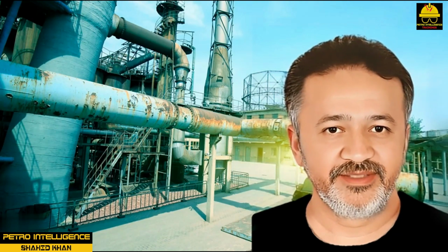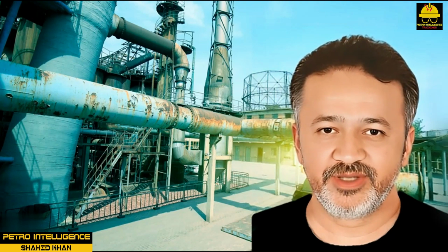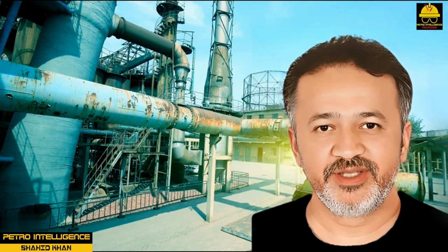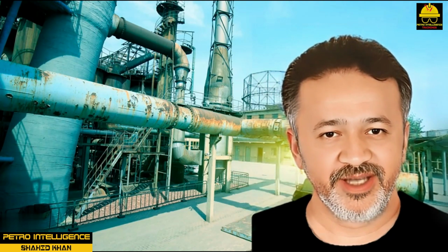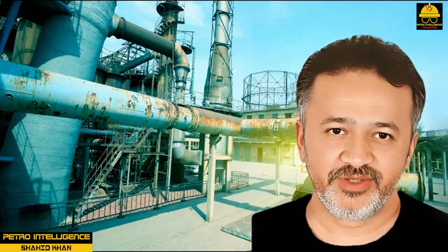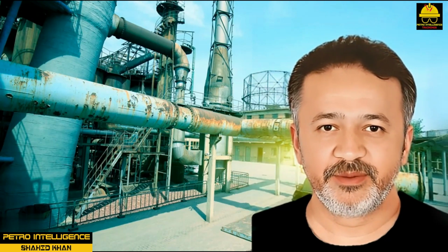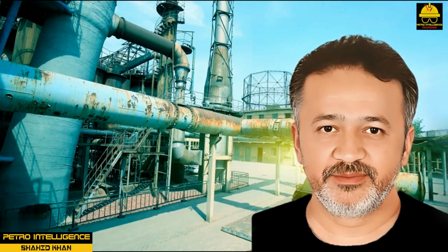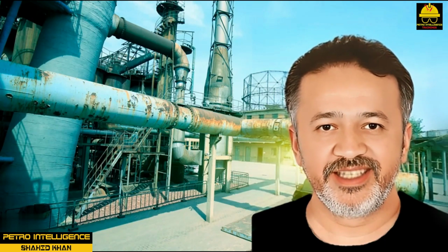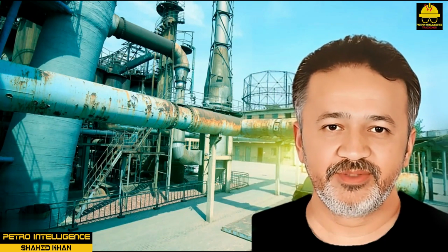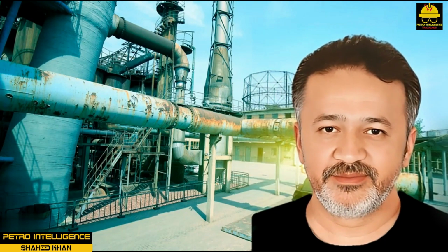All flares have a knockout drum to collect and drain liquids. A pump is usually provided to pump the liquid off to tankage. The technician assigned to the area controls this pumping manually. Usually, an alarm will give a warning when there is a high level in the drum. A high level in the knockout drum can subject the flare to slugs of liquid that will be carried out the tip in the event of a gas release. This situation has resulted in the eruption of flaming liquid from the flare and onto the surrounding area.